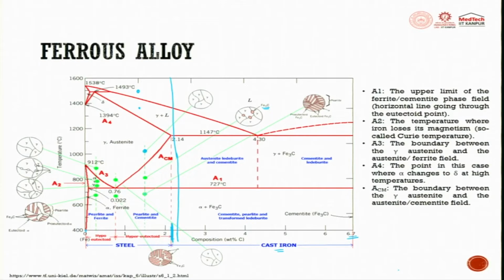When I go down further, the ferrous carbide Fe3C, which was formed along the grain boundary, tries to spread all around and you get a pearlitic phase. You just brought down the temperature, and you see how many different phases are coming.